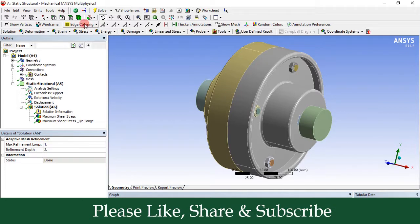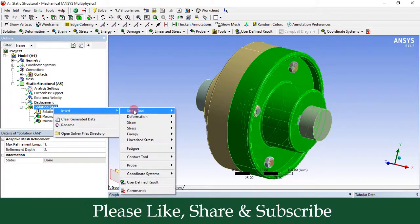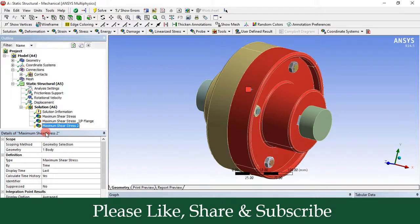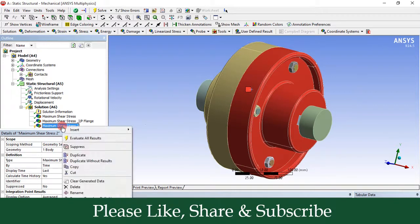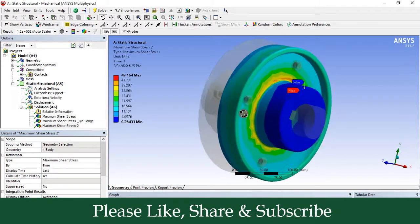So for that purpose again you have to select on this body button, then select the output flange, then left click on solution, then right click on solution, go to the insert, go to the stress and select the option maximum shear. Now we have selected the output flange for this maximum shear stress parameter, so we have to solve this. So right click on it and click on evaluate all results.